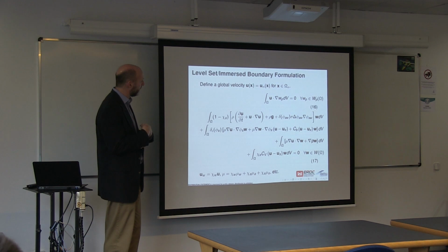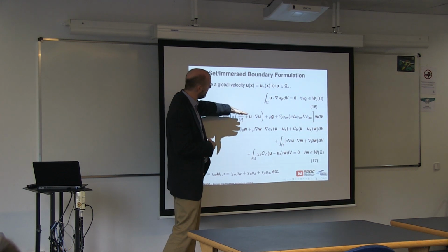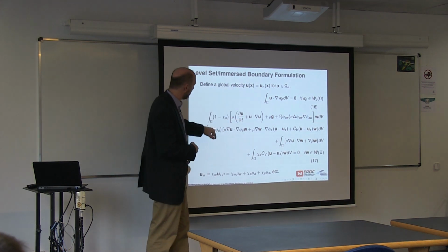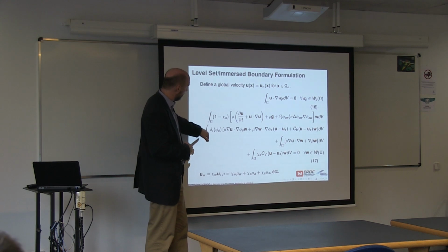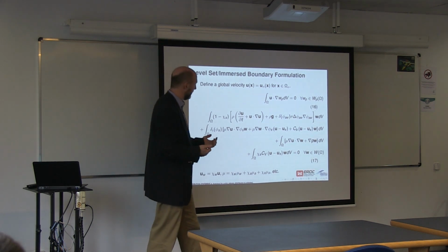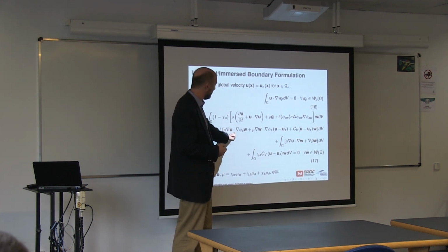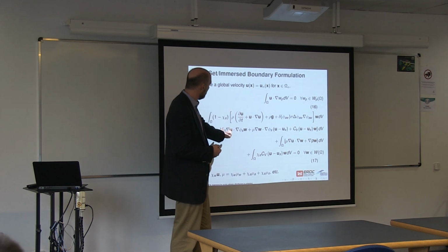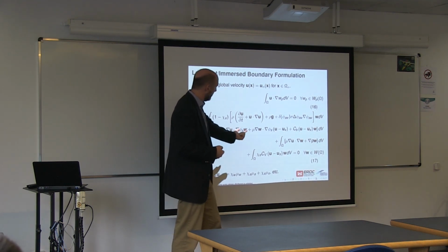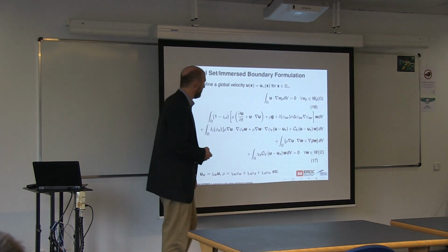And the way that we've been doing that, for the most part, is we take our Navier-Stokes equations, which gives us continuity and a momentum balance, and then we do a boundary integral for our solid surface grains where we represent the no-slip condition, but we enforce that boundary condition using the Nitsche method. So we have, instead of just a simple boundary integral, terms that look like the flux term in the momentum that would arise by integrating the stress by parts, and then we have what's called an adjoint consistency term, and a penalty term that arise from the Nitsche method.